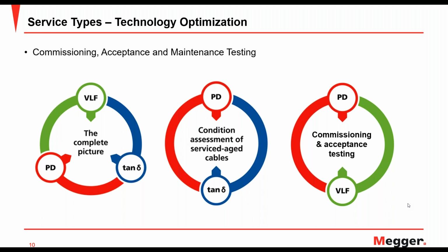So you really want to wait some time while that cable is in service to let those processes take place and settle before you perform your tan delta measurement, as if you performed it on a commissioning test, it really provides no value in trending or any measurement moving forward.